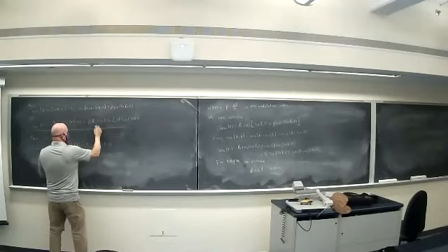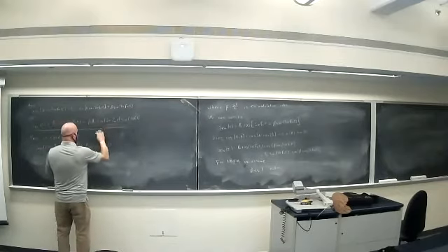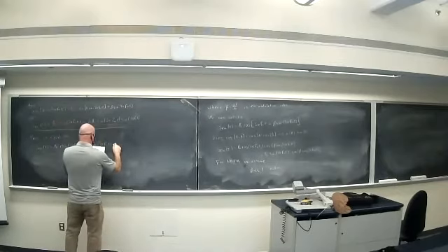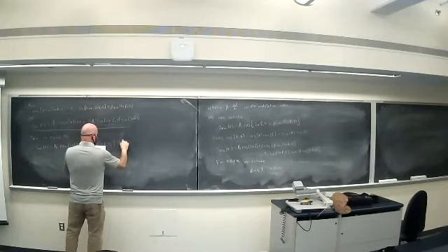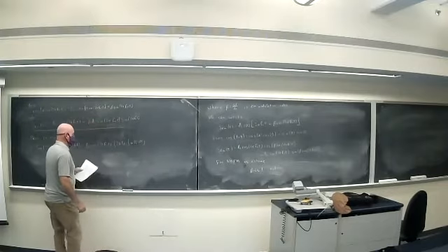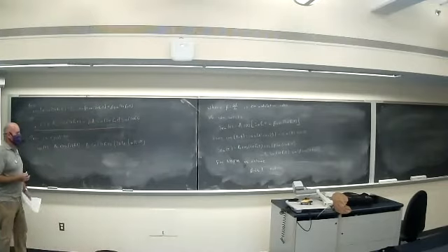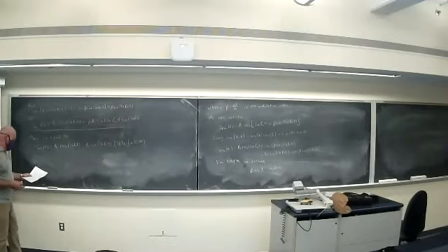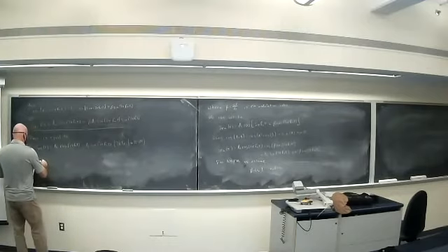And if you look at where this term came from, the sine 2 pi fm t, it was 2 pi kf integral of my message signal. Okay. So it suggests the following narrowband FM implementation.